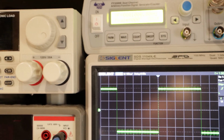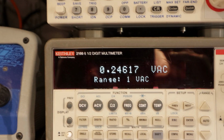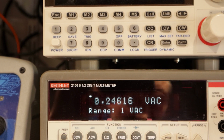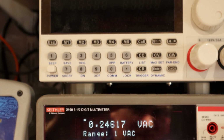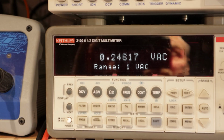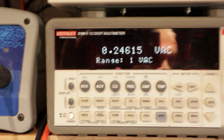it's making little difference. If we go back to the multimeter, you can see that the AC voltage has actually changed. This is because the root mean square of a square wave is different from that of a sine wave. So you can see that the AC voltage has increased slightly.